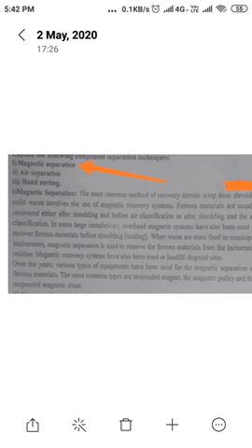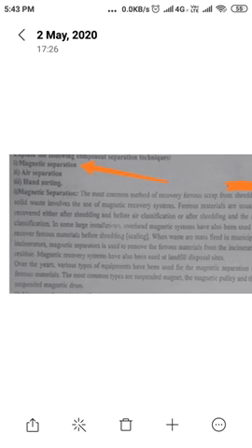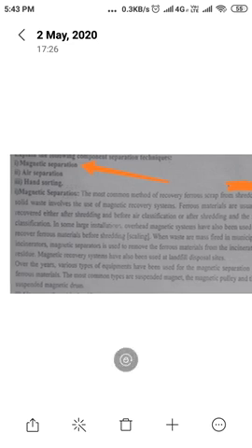Next, for the air separation, air classification has been used for a number of years in the industry's operations for the separation of the various components from the dry solid waste. In this, air separation is primarily used to separate the lighter materials, usually organic matter, from the heavier ones, usually inorganics.